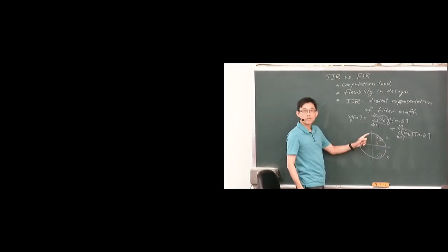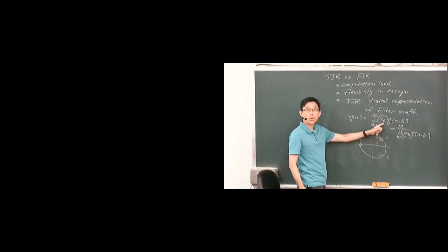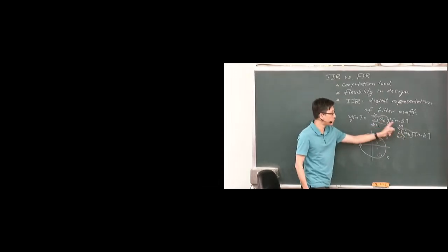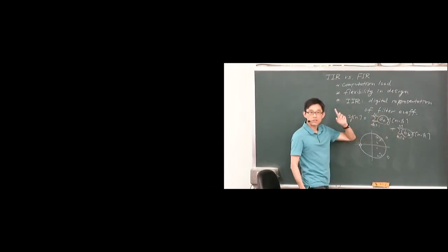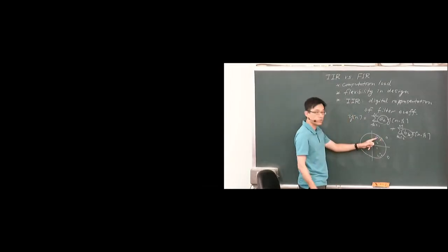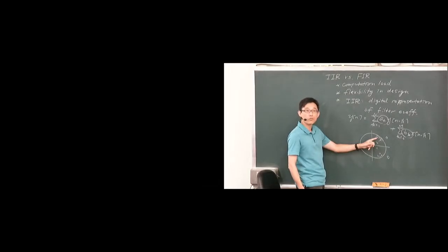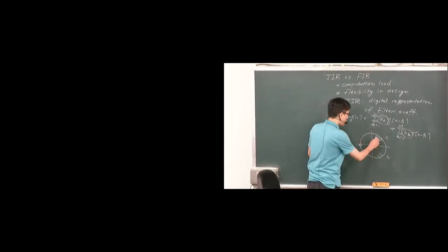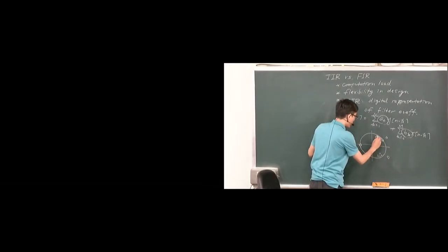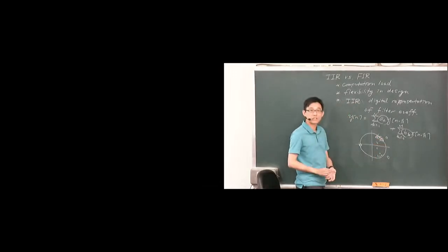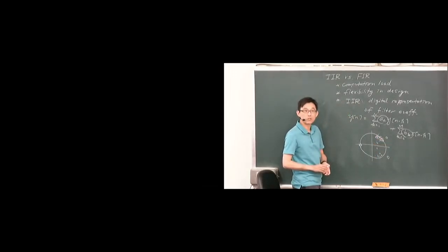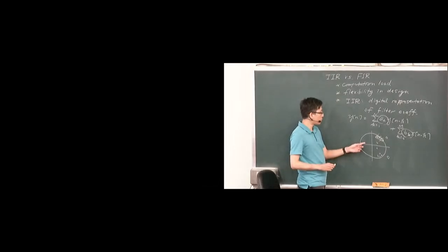There is a danger that after coefficient quantization, when we represent the coefficients by 0s and 1s, some of the poles of the actual system might move outside the unit circle. It turns out that coefficient quantization might cause a pole to move outside in unexpected ways, which is very hard to predict. The bad news is that they get moved in unexpected ways, and we'll cover that next week. So this is a strong motivation why we need to study the structure.